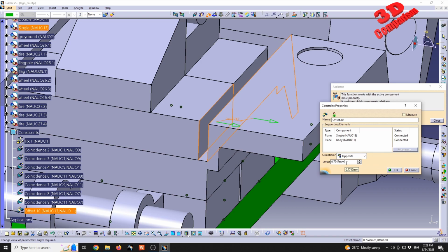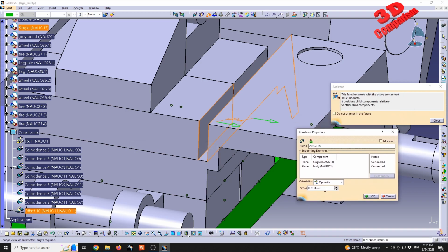Now I have the possibility to add the other distance, which is 801, and afterwards I can select everything, add parentheses, and divide those by 2. And if I press tab, that will update the local value, and in this case we're going to see that this will be the distance.